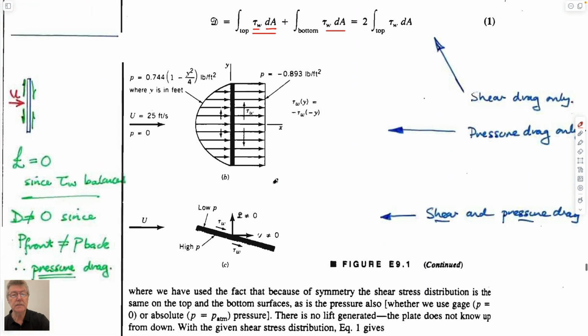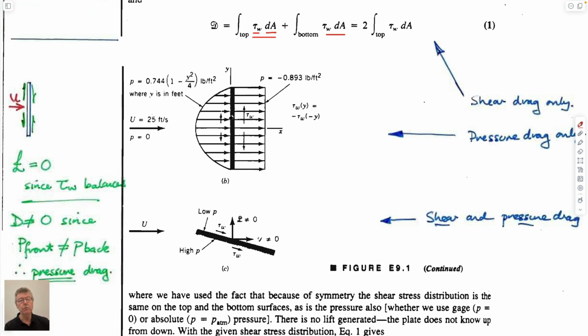You can turn the plate to face the flow that's hitting it, and then in this particular case the solution is given by this. On the front side it's a near parabolic, I guess it is parabolic, form on the one side, and on the trailing side it's a suction, a negative pressure. So this would be negative gauge pressure. So these would be additive because this is acting perpendicular to the plate going downstream, and this is sucking the plate going downstream also.